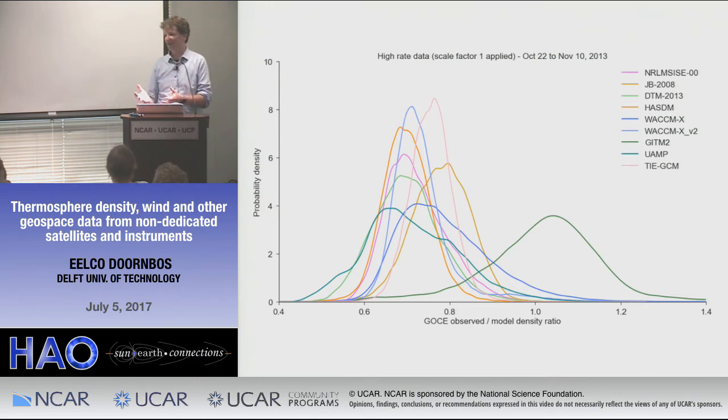Of course, a sphere is also less sensitive to, for example, temperature variations. These satellites do not have sensors that measure the temperature of the gas, and the temperature of the gas also has an influence on the aerodynamic model parameters. And the more elongated the satellite shape, the more sensitive these aerodynamic model parameters are, because of the random thermal motion, they bounce on the surfaces that are parallel to the flow. And for a sphere, you would have reduced that problem. Yeah. But there are many spherical satellites, not with accelerometers, but with very precise tracking as well, that are also used for aeronomy.